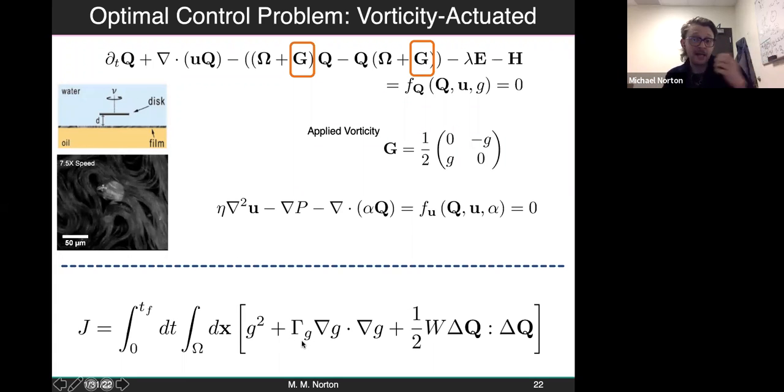I didn't show any of the other kinds of solutions you can get, but by varying W and varying gamma, you can create much more. If you really increase W, you'll get much larger control inputs, and it'll really try to force the system. It will use less of the native dynamics of the system in getting to the other attractor, because it's just going to try to wipe out whatever's there to force the system into a new state. The lower the W, the more graceful it will be. It will try to use manifolds that are already there in the system. That's very hand wavy, and you have no reason to believe me, but that's at least what we found for the oscillator network.